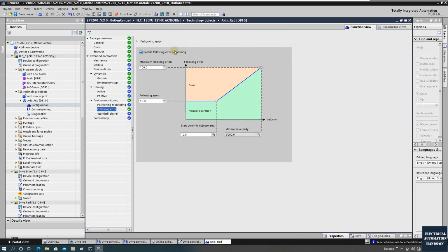At the very beginning, especially while you are using a tool with high inertia, I would recommend disabling this selection, or at least setting a higher value on this window. Otherwise, at the beginning, either you travel in the wrong direction or your closed-loop positioning hasn't been tuned perfectly yet, and in some cases you will find a lot of following errors.